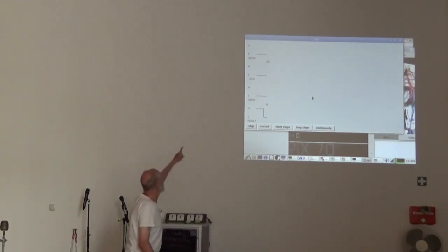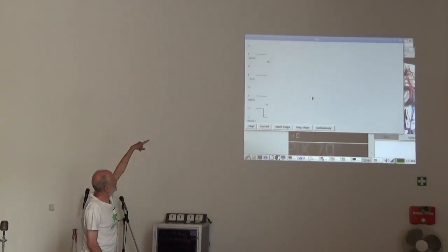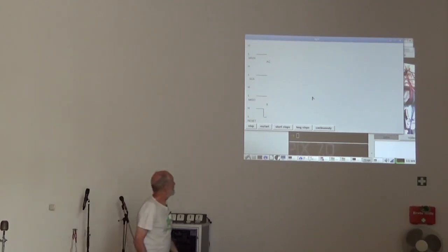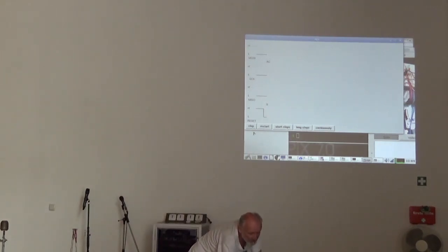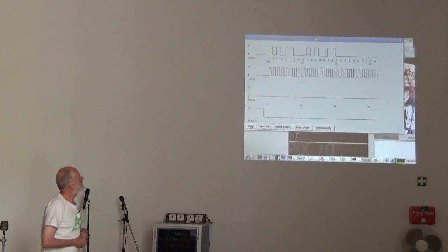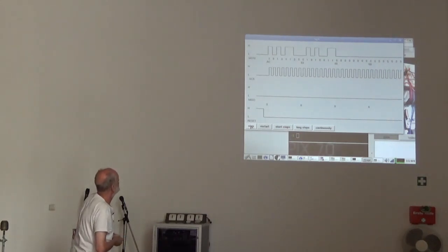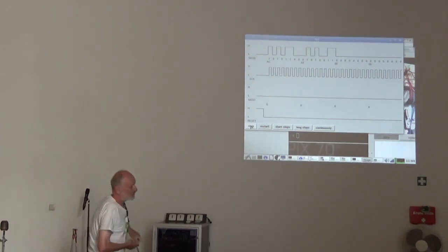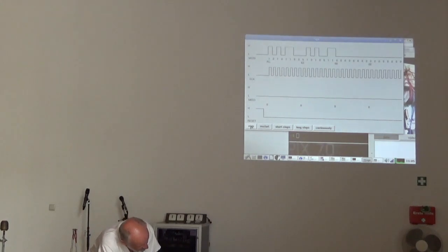Maybe first with the SPI bus, in this case the signals are low all, and also the reset has been set to low, and when I send bytes to it, I have always sent a sequence of 4 bytes, then oh, it doesn't work. Because normally the chip must respond.